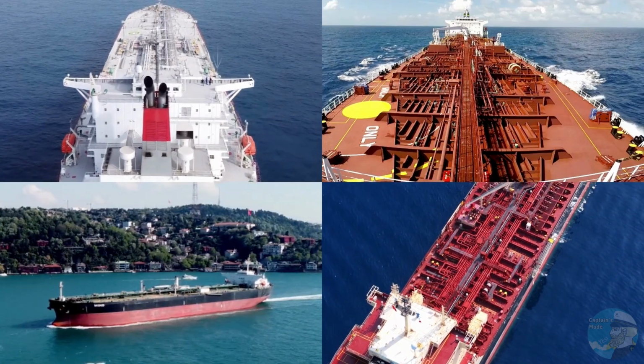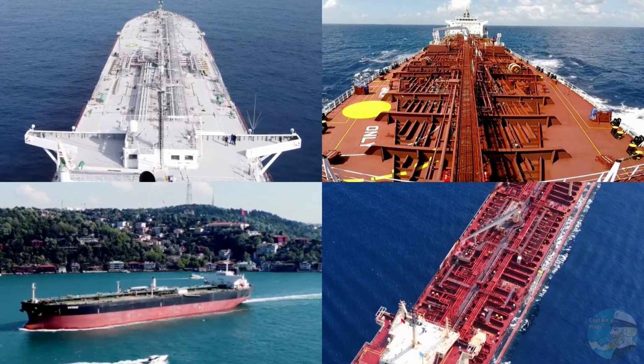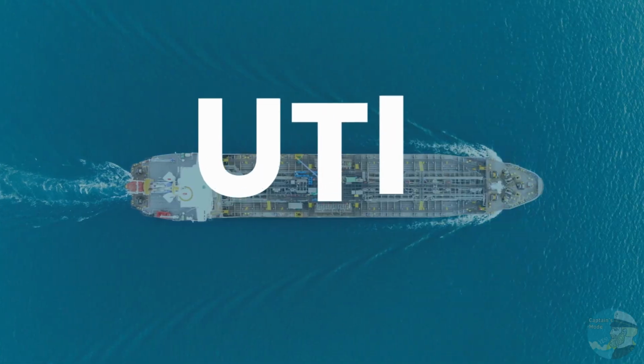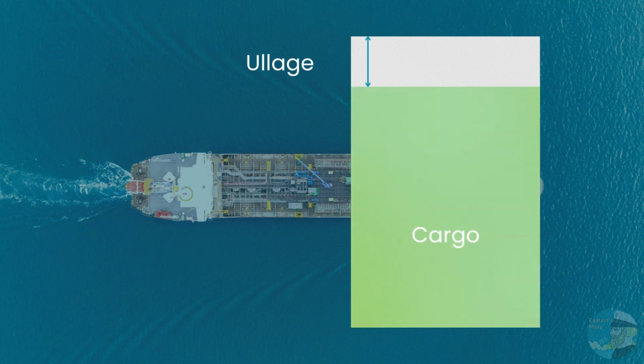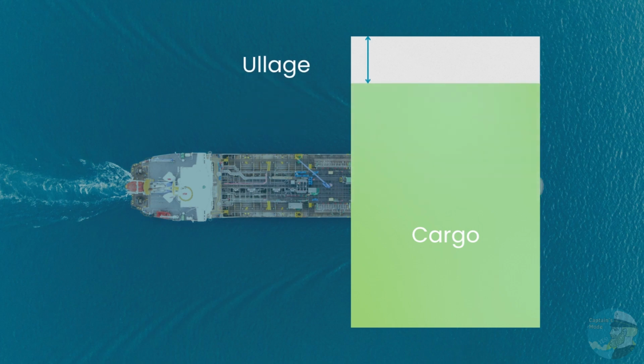To minimize these errors and agree on measurements with cargo surveyors, seafarers use UTI or Ullage temperature and interface to determine cargo quantities inside each tank. Ullage is the empty space from the liquid surface to a fixed reference point, usually the tank's top datum. It tells you how much cargo is in the tank by indicating how much space remains unfilled.